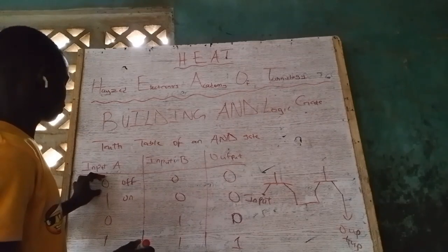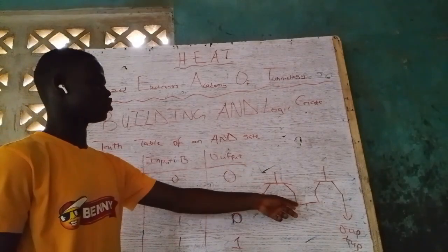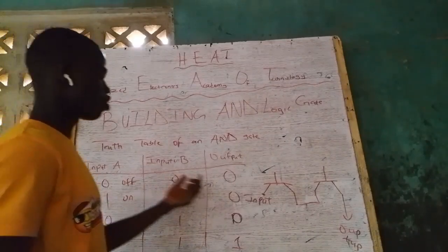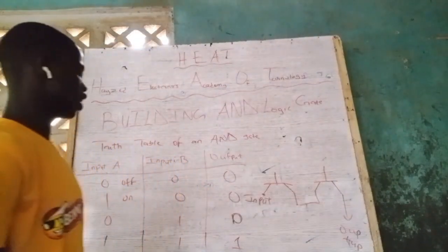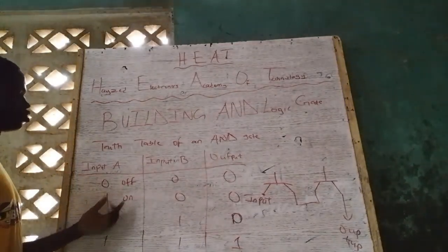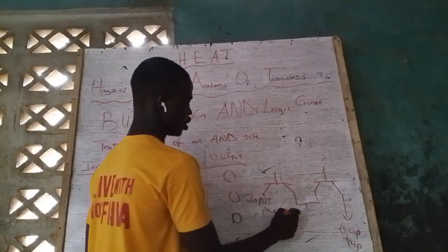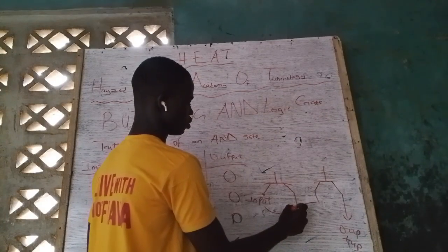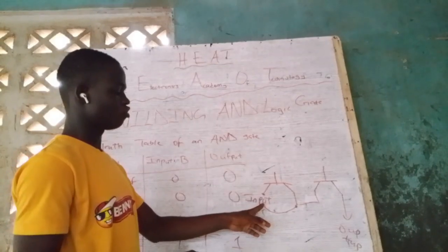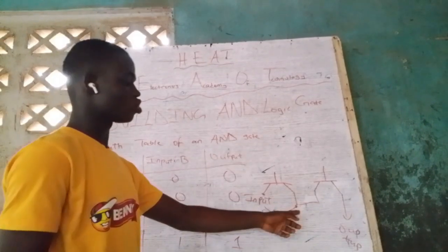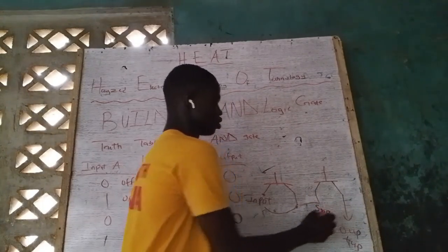If transistor A is off, nothing can flow through from here to this place. If transistor B is off, nothing can flow through from here to this place. Now let's imagine transistor A is turned on. That means our input is going to be able to flow from here to here. That's because of what? Transistor A was turned on. So our input was able to what? Flow from this point to this point. Then it will continue and move here to stop at this place.